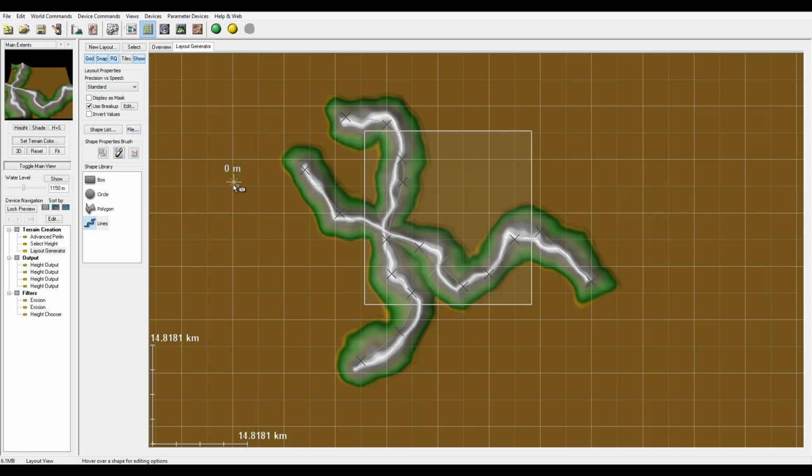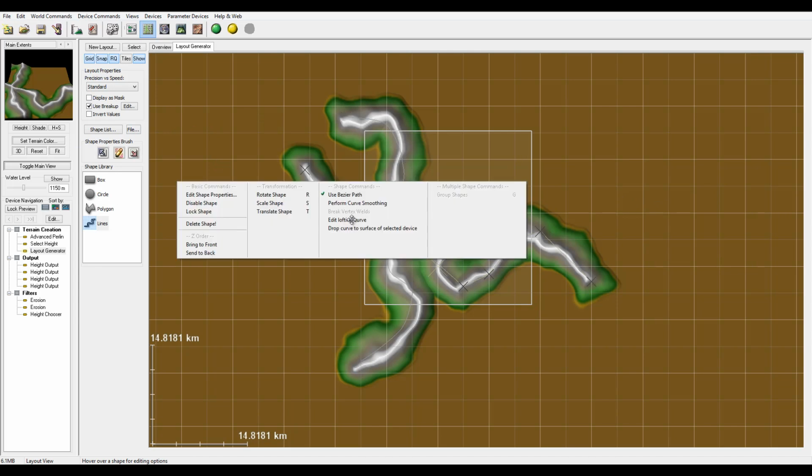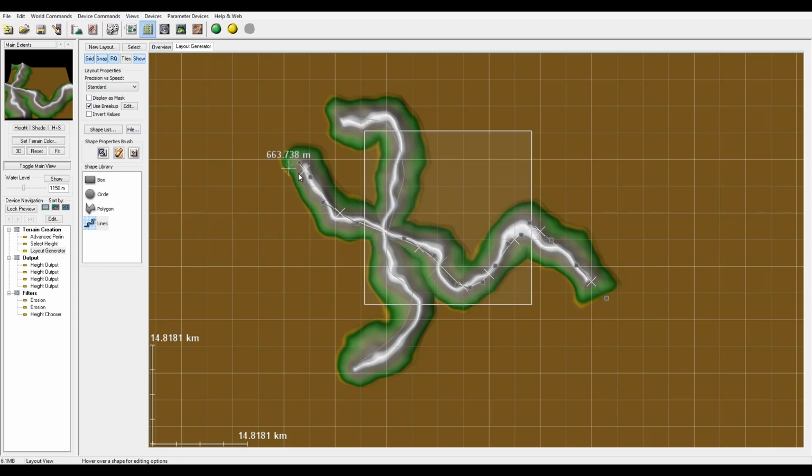You can notice it has the same options. Again, I right click and choose smoothing, just to make it a little bit nicer. It adds these bezier lines, so it makes it smooth and nice. And if you think it's a little too noisy, you can just reduce the roughness a little bit, so it becomes less rough this way.